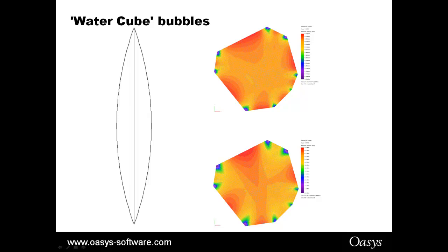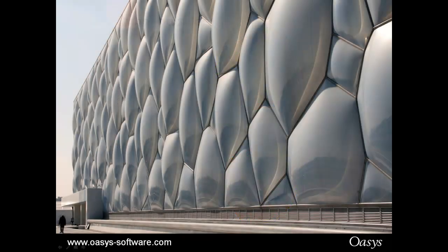Now, they needed a form finding to begin with because for the large bubbles, the ETFE would yield under the inflation load, and so they had to be form found and then with the cutting patterns applied to get the right shape. Then, once it's under load, you then use static non-linear analysis to check them for inflation and wind loadings. End result: over 8 major international awards, and so on. And by the way, you can also use this inflation method for forming domes and grid shells. Just in passing.